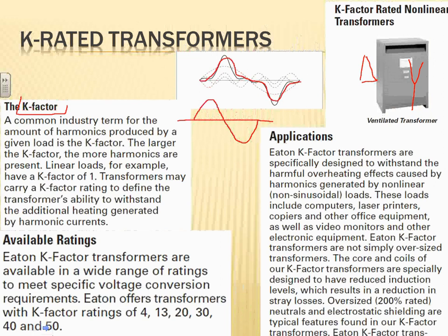When it's a K-rated transformer, say K13, they design them in a way that they're basically more robust, with more insulation between them. One way is to handle and absorb the heat generated and circulating inside the Y, and another way is to cancel some of the harmonics, they call it mitigation. Long story short, your equipment will live longer and function properly. So every time you have a 208/120 transformer, you want to specify some type of K rating. The higher the K, the better the transformer and the more expensive.